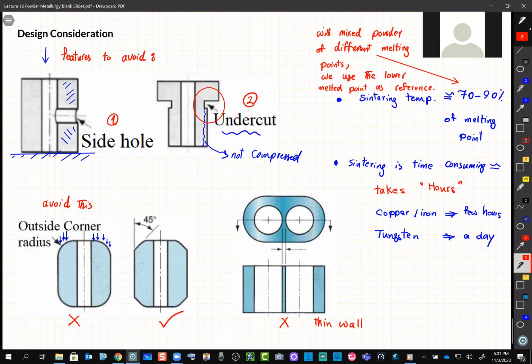Will we need more time to sinter it if they're that different in temperature? The second one, let's say the higher temperature, we don't want it to be melted. The first one acts as the binder. If they are close to each other, let's say you are mixing two things, 1000 C and 900 C, then there is a chance that the outer surface of the higher temperature particles also gets to that melting point and they fuse together.